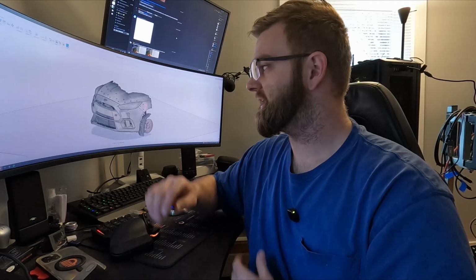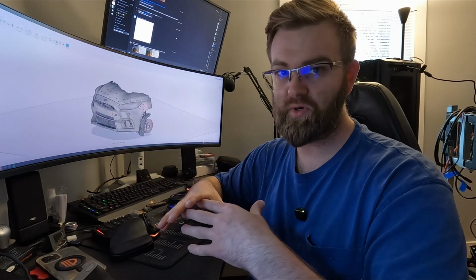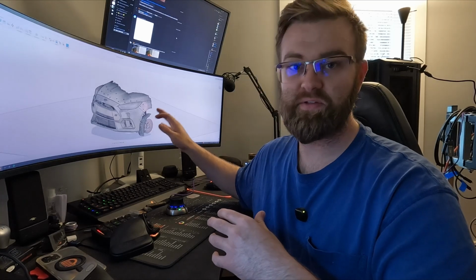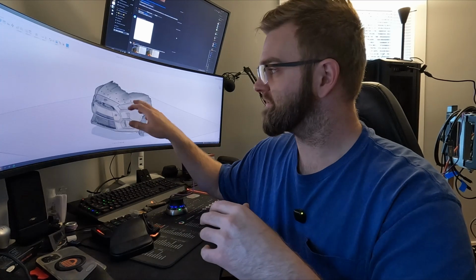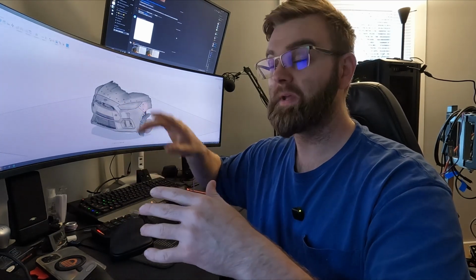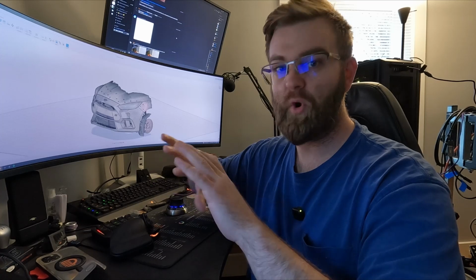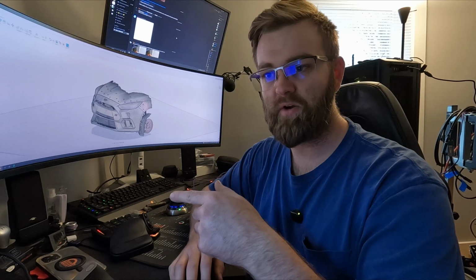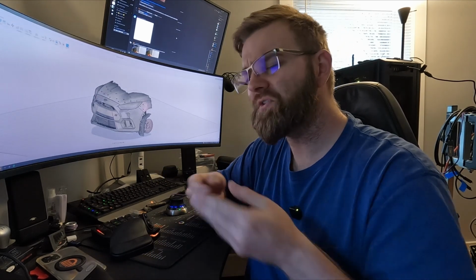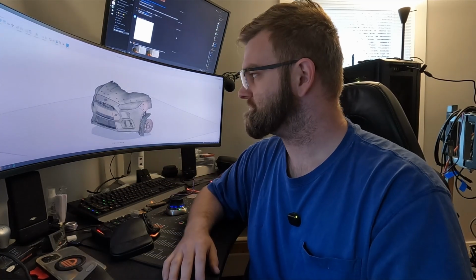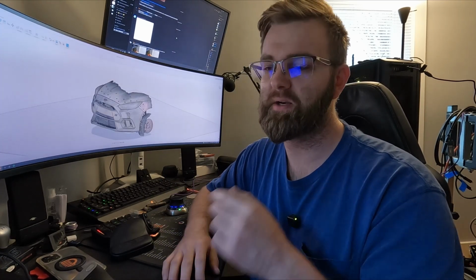And so that's really helpful in taking your scan data, bringing it into a coordinate plane, so that way it's all oriented around the same point. And then you get to use point features at major components, major points on the component, and it overlays them, gets them as close as possible within some margin that you get to play with. So I'll show you how that workflow goes because it's free. And as Making for Motorsports said, it's free. And that is nice when you're trying to do stuff on a budget. So it does limit you a little bit in your capabilities. So I'll show you how I get around that.